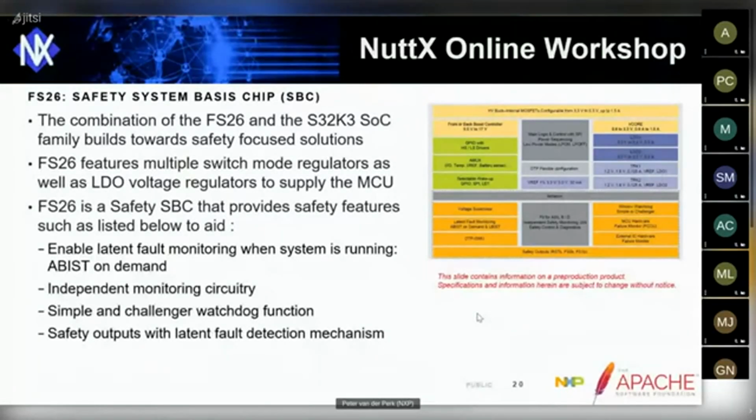And what the FS26 can do is that it's connected to the FCCU and FCB pins directly to the MCU. And if there is a fault occurring, or you have these on-demand built-in self-tests of hardware and it fails, the power supply can even reset the MCU.